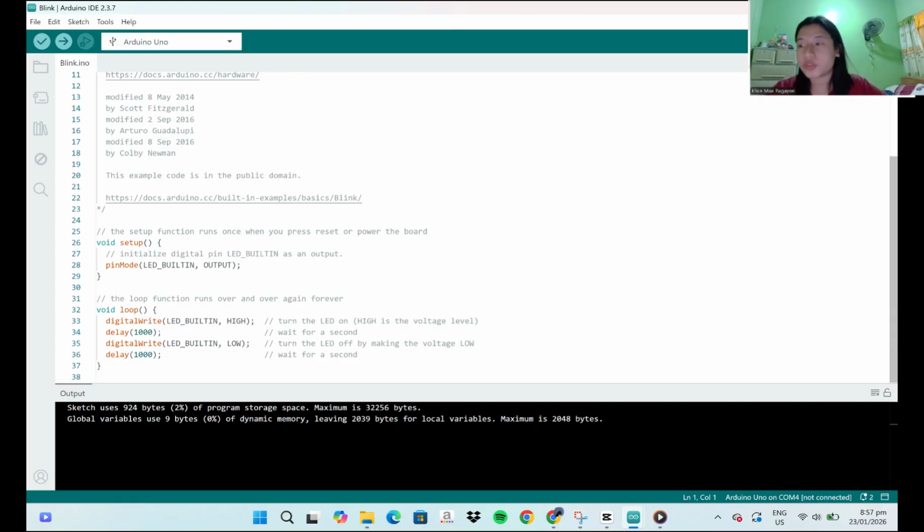So now, let us create a simple Arduino program and breadboard circuit that will perform the following function. If the switch is not pressed, the two LEDs must be both turned off. While task switch number 1 is being pressed down, the two LEDs will blink alternately. Only one LED will blink at a single time. While task switch number 2 is being pressed down, the two LEDs will blink together, simultaneously. So let us now create the circuit that will demonstrate that program.